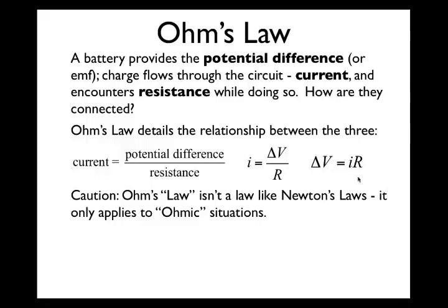Well, I guess in some way Ohm's law is the same thing. Ohm's law only applies to situations which are ohmic, which is a very circular argument right there. But what that really means is Ohm's law works when the resistance of the object that you are using as the resistor in your circuit is constant or very nearly constant. And some materials, turns out light bulb filaments are among them, change their resistance as they heat up and as different amounts of electric charge flow through them.